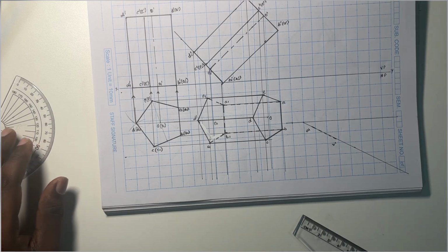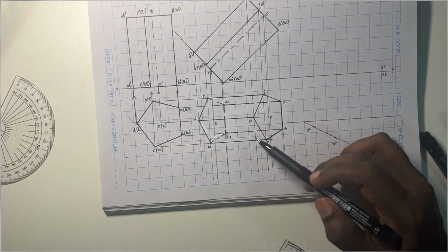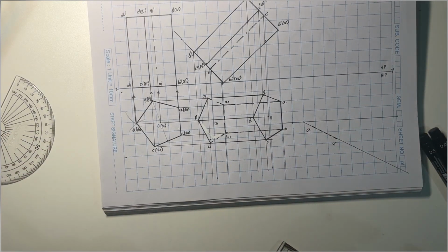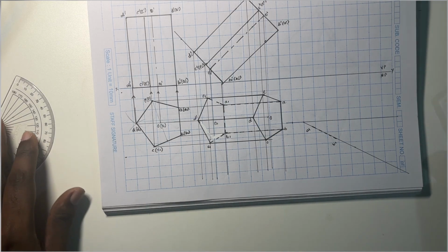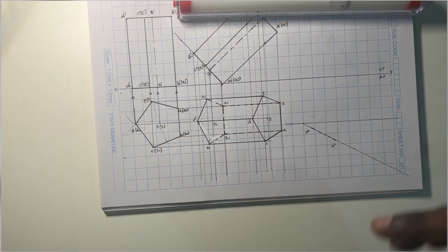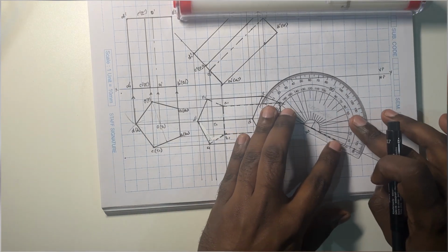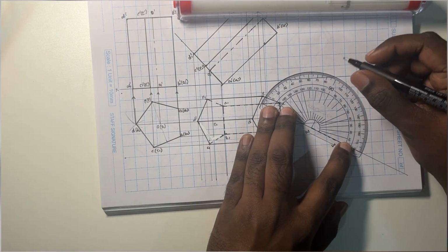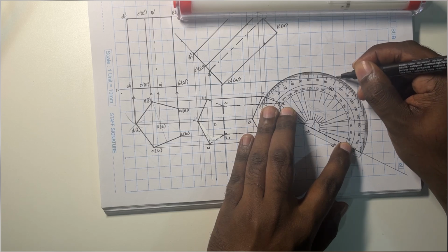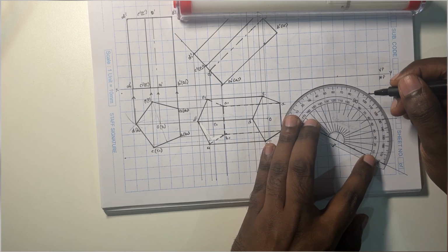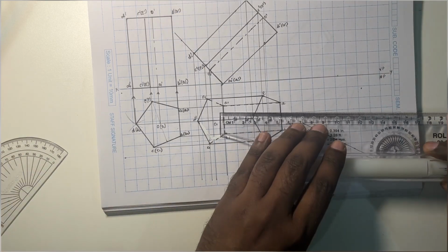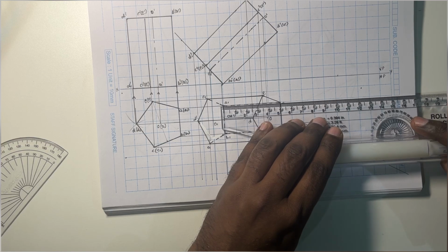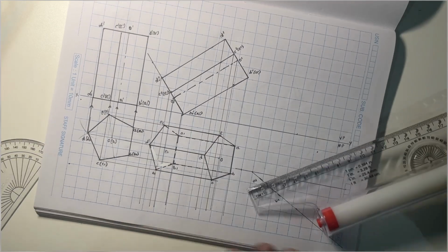You can just see that A1 to A and B1 to B are all straight lines, that is, they're all at 90 degrees. So let me draw them as 90-degree lines. So I'm going to measure 90 degrees from both the corner points. And also from B1, I'll mark 90 degrees and I'm going to transfer these points. So let me take the measurement from A1 to A, which is equal to around 5 centimeters.